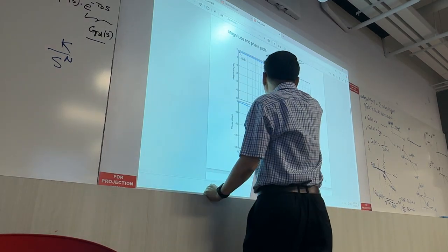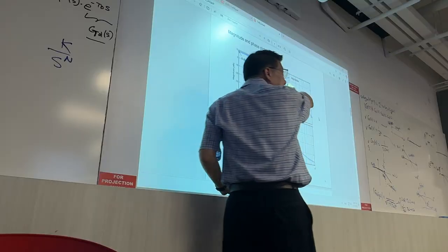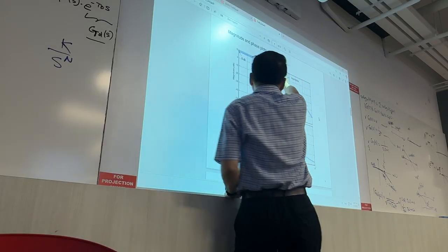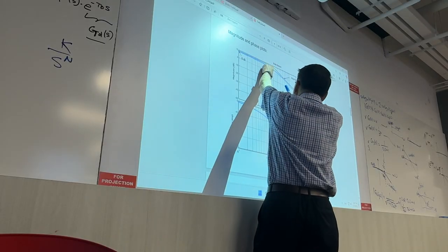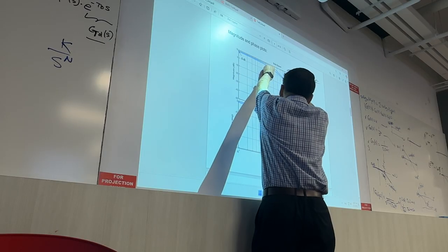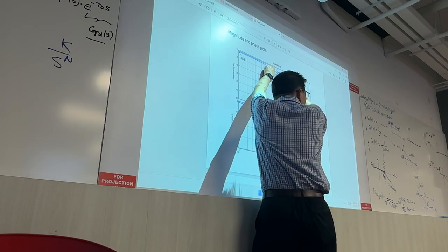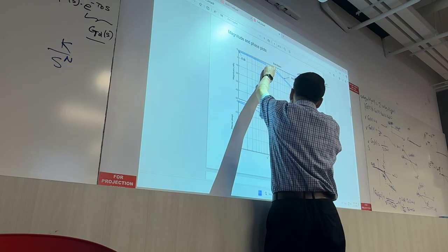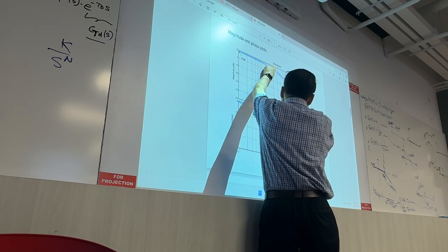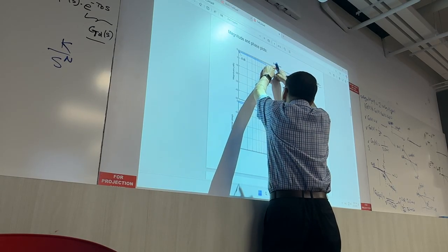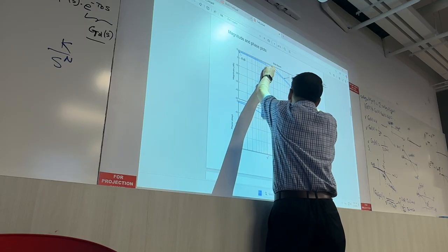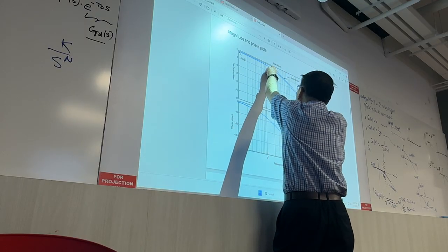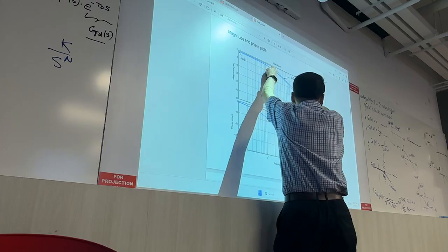Now this is a bit tricky, huh? Look up here. So from this 20, how to draw this minus 20 dB per decade? One way is 2 to 20. This is 1 decade change. So this 8 and this must be corresponding to minus 20.